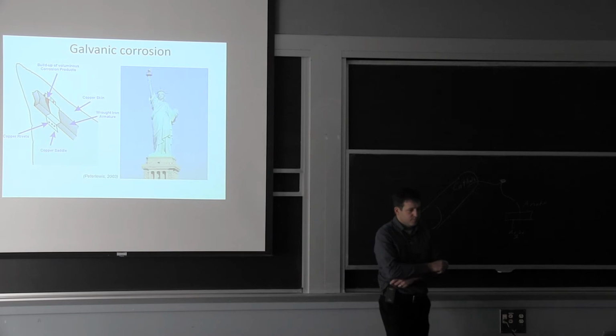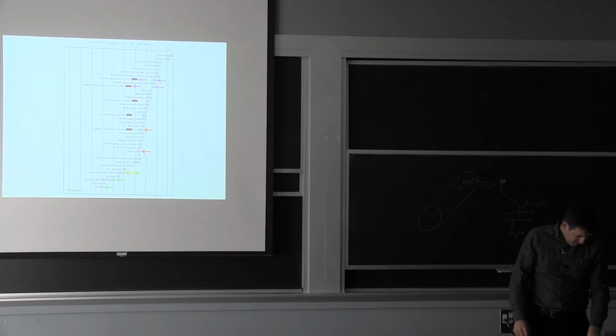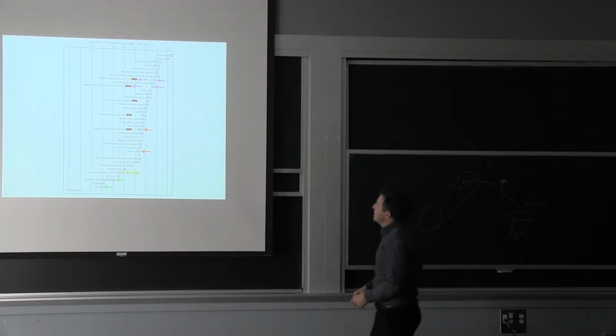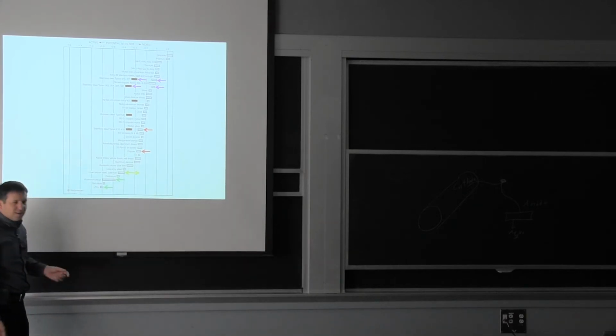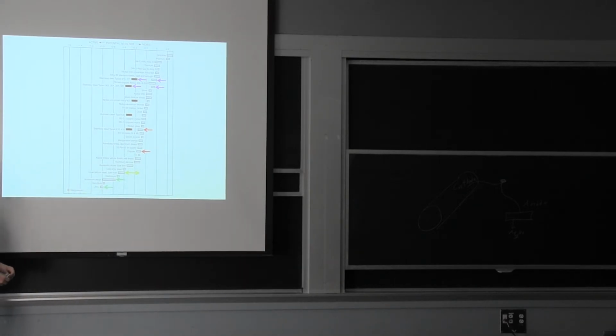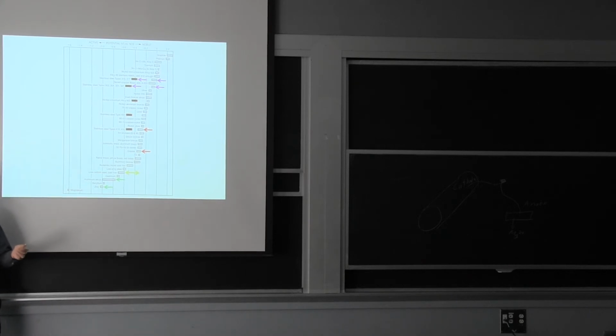Yes? So I'm still a little bit confused how the earlier chart that shows you the active potential relates to this. Okay, so the galvanic series, I put it in because it's what typically you see in a galvanic corrosion class, but we don't want to emphasize all the intricacy. So the story is, this is done in salt water where you put the two metals together and you see what potential is generated between the two, how much they interact with each other. It's like if you're trying to design a battery, you go through this and you say, oh, this is a great battery type of situation.